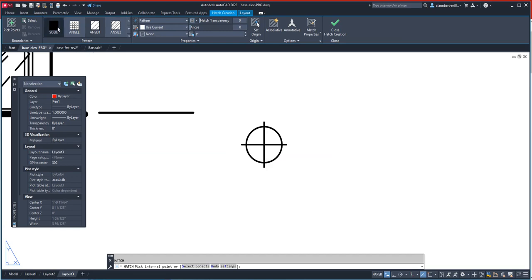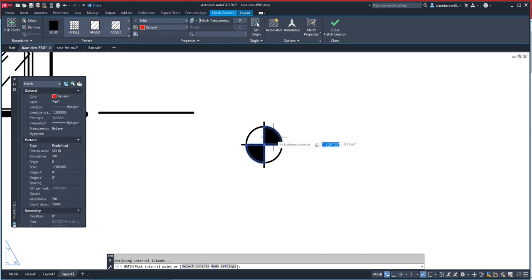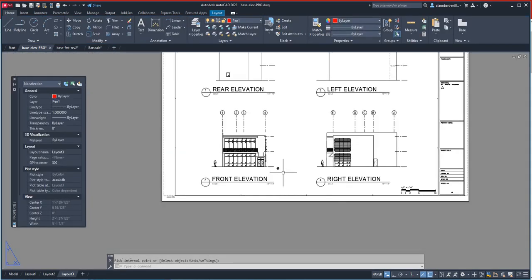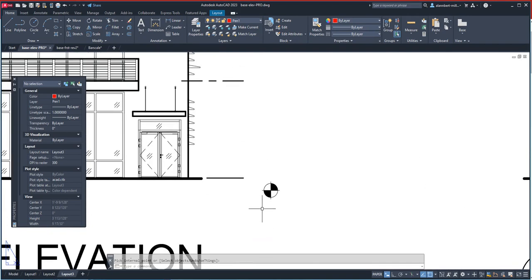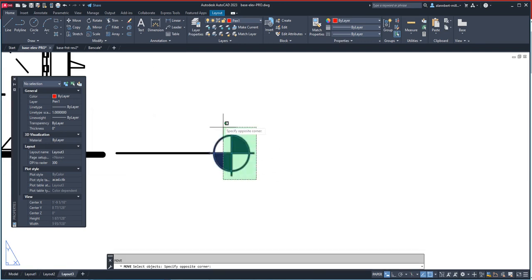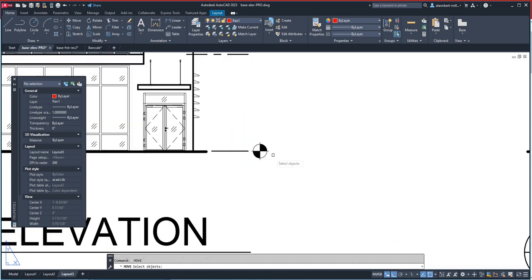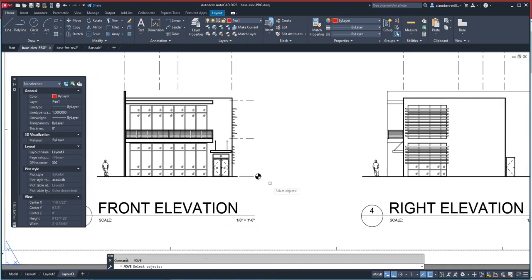And I wanted a solid hatch, and I simply click this and that one, and that's your datum plane. And then you would put that somewhere here. Sometimes you would see that it's a little bit removed by a little bit of distance. There's a gap like that, and that datum plane would establish your finished floor.